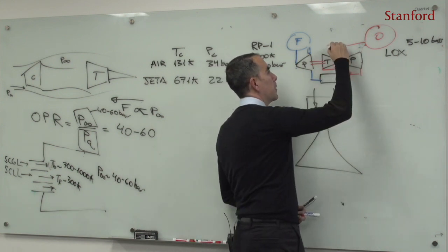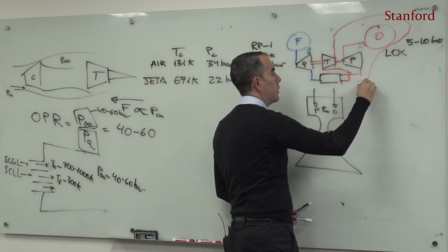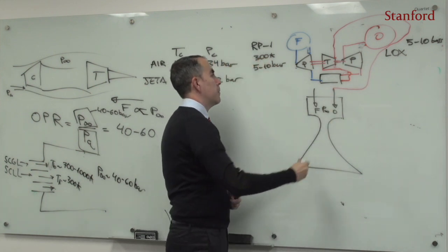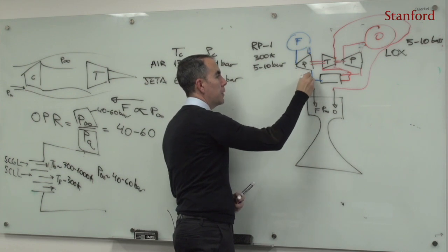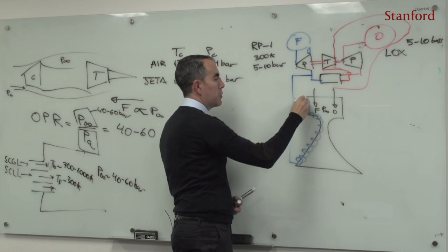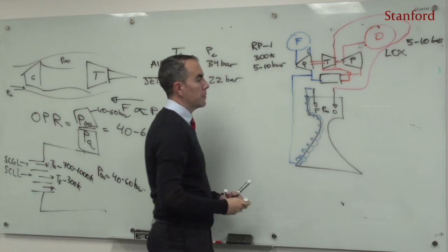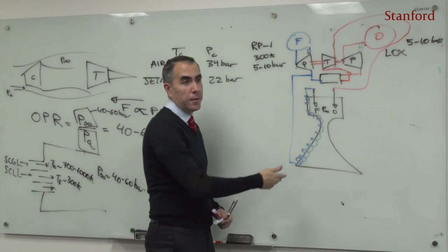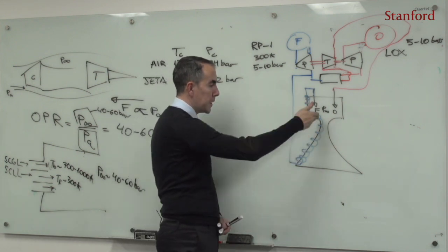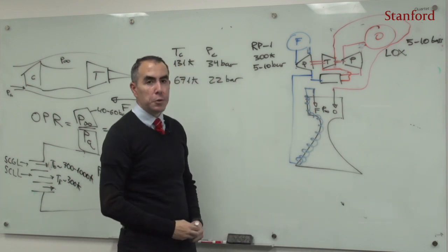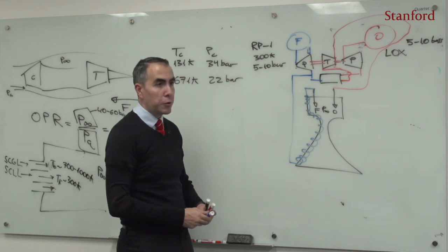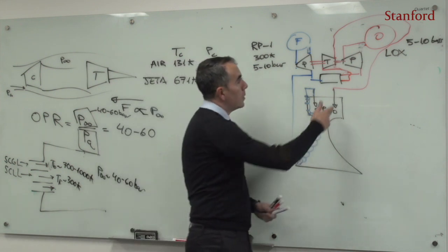And then you take the result, I'm going to take it over here, and then you send it to the combustor. So here you take the fuel, right? Part of this fuel, you pass it through the nozzle and through the chamber, and then you inject it there. For those of you that do wall modeling, I could tell you about a fundamental problem that arises near the throat, related to the curvature of the throat in this cooling channel. If you are interested, feel free to ask a question during the questions time.